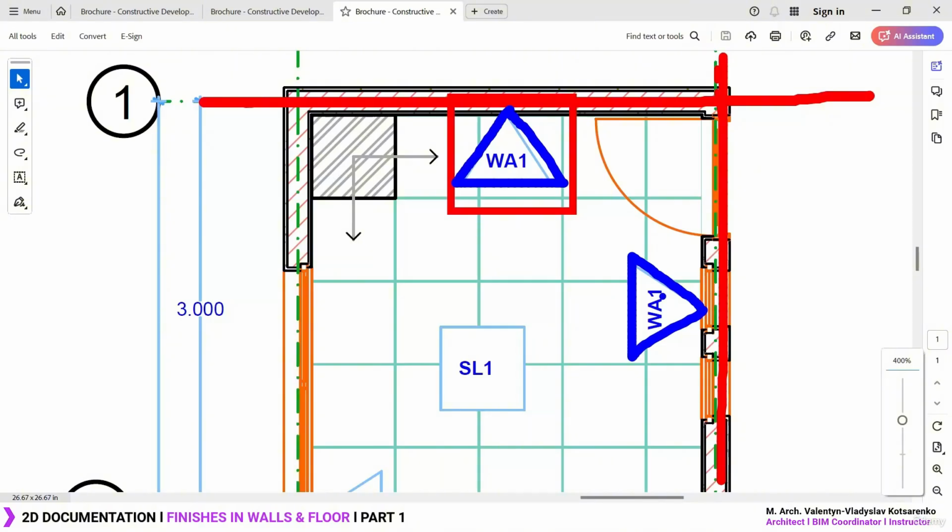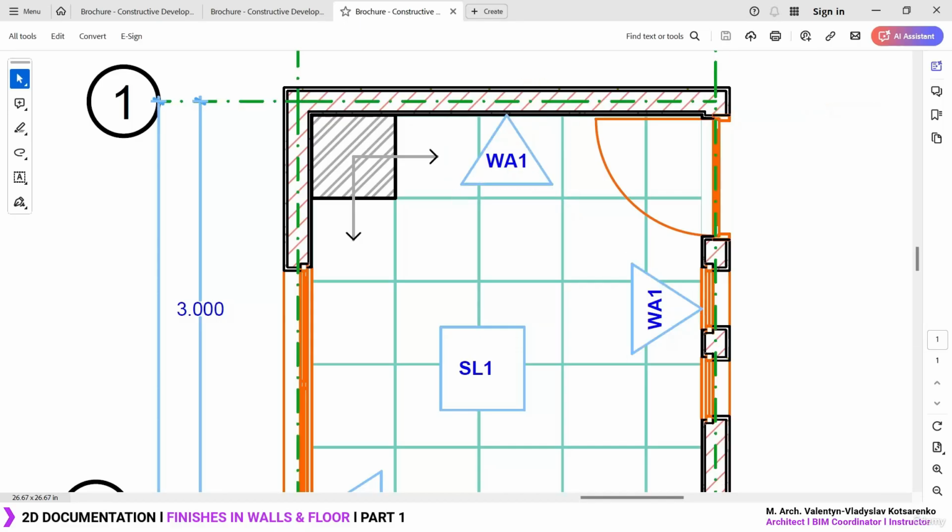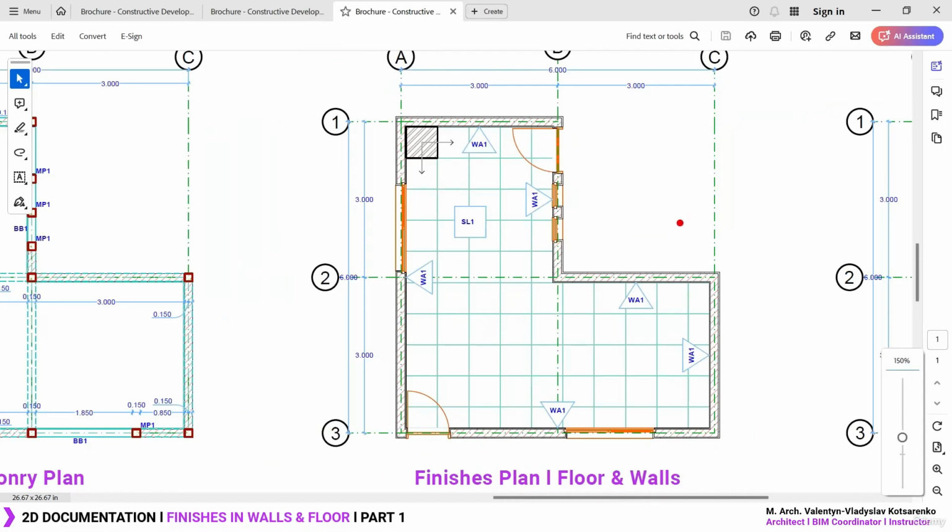And you can program the ID to be inside the label, so the label is going to read the ID we have for the composite, which is quite amazing because traditionally what we usually do is copy and paste each of the different tags or labels one by one, and then we need to also orient or rotate each of the labels one by one, and this is extremely time consuming, something you can solve almost instantly by the automatic labeling function.